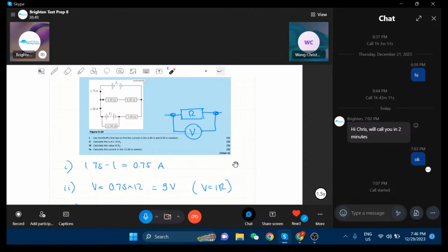So it's not so simple as it seems at first glance. I agree with you, and it's tempting to consider this one for the whole circuit. However, in this context, it's a bit of a different story, as we have a second EMF on one side. We have a given current from the first EMF, and that has an impact on what's happening for the rest. And I think a good approach is to make this mental split and say, okay, this is like a subgroup on its own, which, as it is in parallel, must have the same resistance in it.